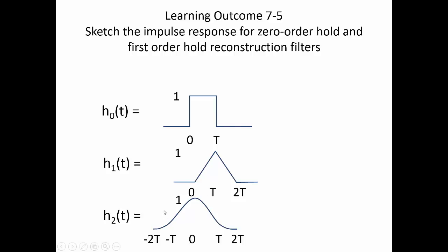So in practice, that's what we do. Instead of using the impulse response h1 that's centered around 0, we shift it, and we accept that as engineers, our response will look the same, but be shifted in time. Well, what are we going to have to do here? Now we have to shift it by 2T units, or at least 3/2 T units, in order to get this to be causal. We can do that.